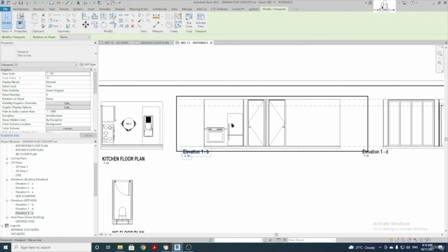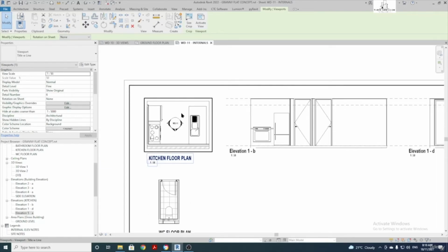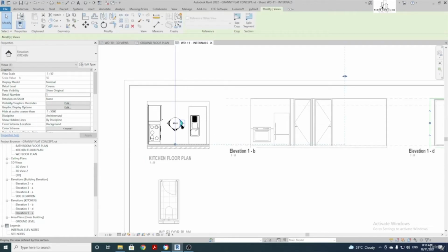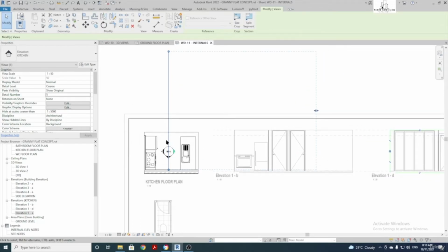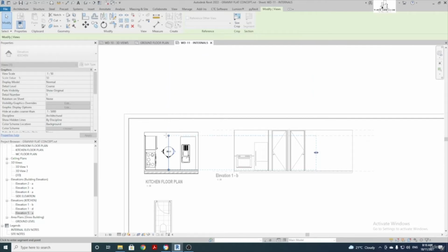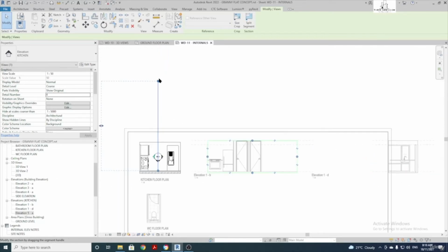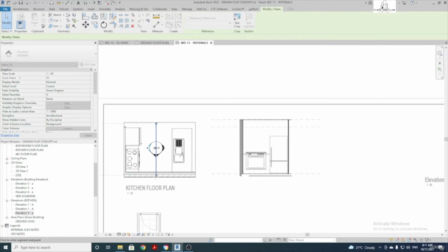Now you can resize these a couple of different ways. You can do it by double clicking this floor plan here, clicking on that view, that little arrow, and you can see this line is being created. So you can drag these blue dots in, and that'll bring the elevation in to where you want it. You want to have it just past this bench here, and the other side too. You can grab this blue dot, drag that out outside of the wall if you want to show the wall in the elevation. You can do that for all 3 of these elevations. So this one as well, drag that into where you want it. Same as this one here, so it's coming out way down here. We want to bring that right in just past that bench, like that.